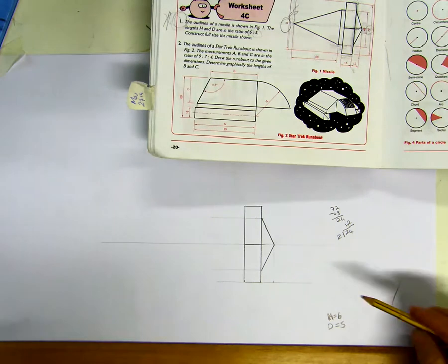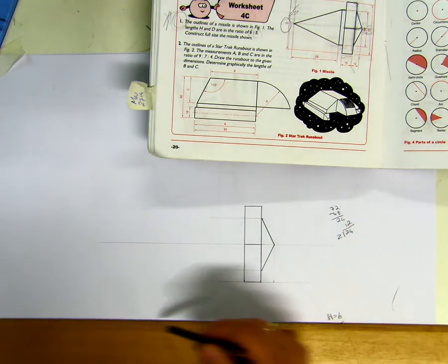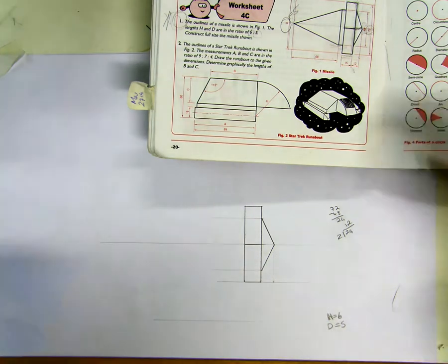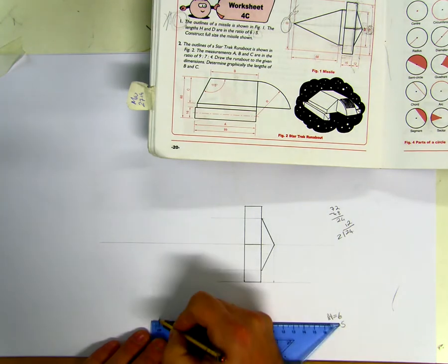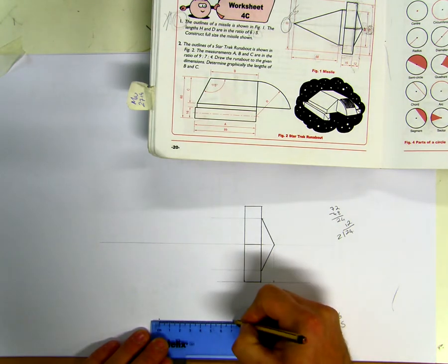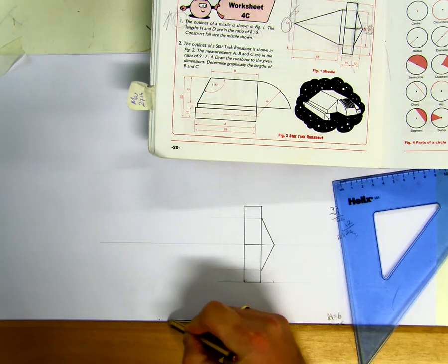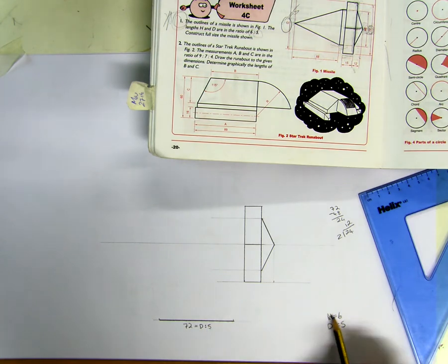So the first thing we're going to do is, we can do it on our drawing, but to keep it neat and to make it easier to understand, we're going to draw a light line down here, and we're going to measure. So we can see D here is the ratio 5 and is 72. So I'm going to draw a line down the bottom here, 72. So this is 72, which is D, which is a ratio of 5. So we just draw a line there lightly. So we know that this is D and it's 5 ratio, so H is 6.